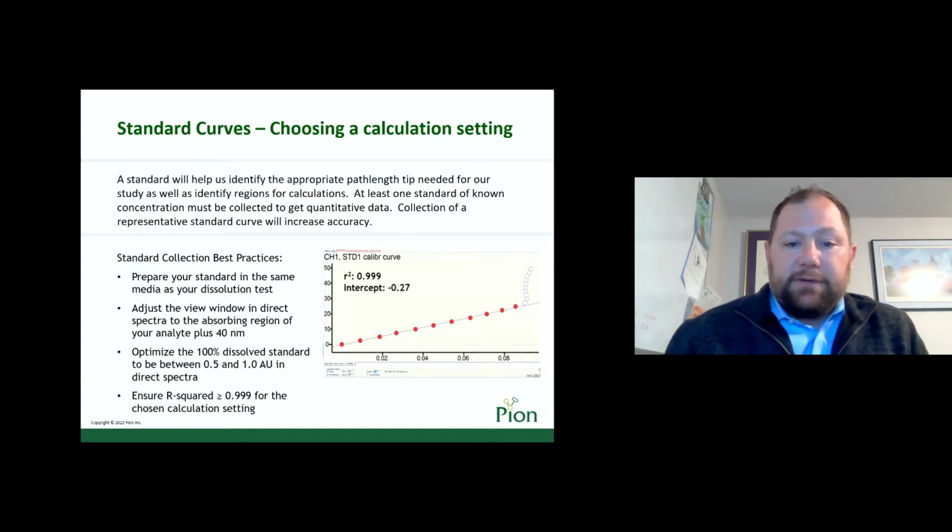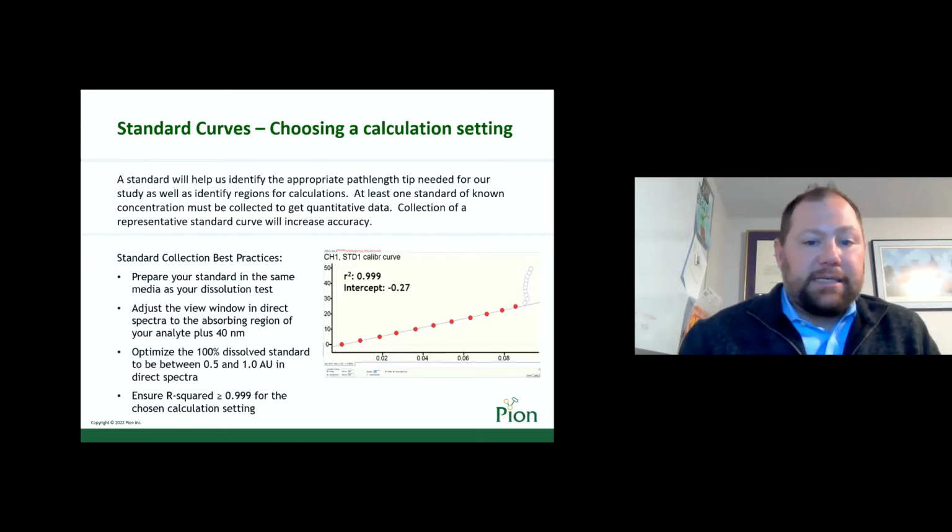The rainbow is a relative absorbance instrument, which means that a blank and standard need to be acquired for each channel with which you intend to collect samples. The software needs at least one standard spectra to be collected in order to calculate quantitative sample data. You can collect as many standards as you want, and beyond one point, AU Pro will calculate a standard curve, which will give you more information about your API, as well as give you more confidence in the quality of